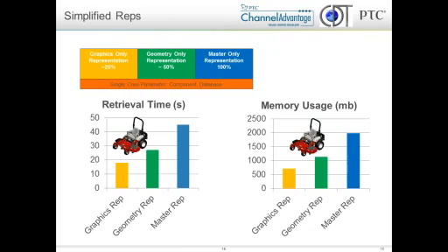When opening a large assembly, I can choose to open a simplified rep of the assembly. Instead of bringing in all of those details to the master rep, I can choose to create new reps that only show a portion of the data. I can even make a rep that excludes all of the internal components of an assembly and only shows the external components, very similar to the envelope feature that we just were talking about. For now, let's focus on the graphics rep.